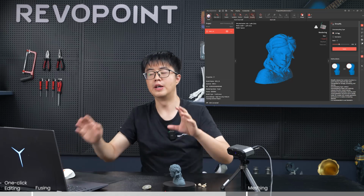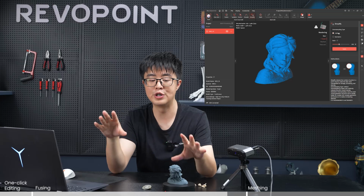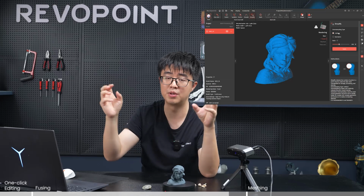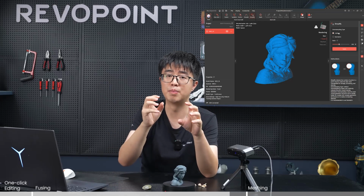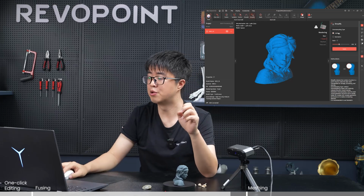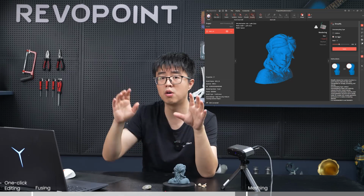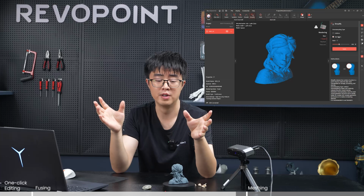So uniform will simplify your 3D model very evenly. It doesn't matter which part it is, it just divides the 3D model into a lot of cubes and shrinks the points evenly. But geometric means it will only shrink down the areas that do not have a lot of features, like the shoulder. It will not shrink down much when the areas have a lot of details. So it really depends on which type of 3D model you're scanning.